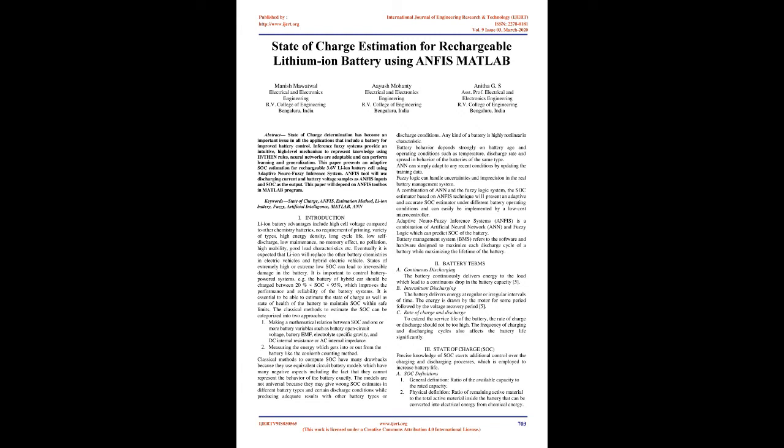This paper presents an adaptive SOC estimation for rechargeable 3.6V Li-ion battery cell using Adaptive Neuro-Fuzzy Inference System. ANFIS tool will use discharging current and battery voltage samples as ANFIS inputs and SOC as the output. This paper will depend on the ANFIS toolbox in MATLAB program. Keywords: state of charge, ANFIS, estimation method, Li-ion battery, fuzzy, artificial intelligence, MATLAB, NN.